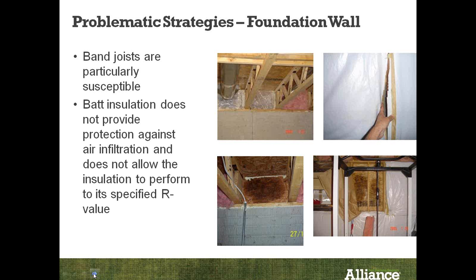And then on the top left is something very similar. The builder insulated the between floor system with a rigid board product. And the same scenario here, he put an extra layer of bat insulation over top of it, but it was still condensing on the foam board layer because that bat was cooling that surface off, but still allowing moisture to diffuse through it and condense on it. Obviously, there's no drywall in these scenarios.